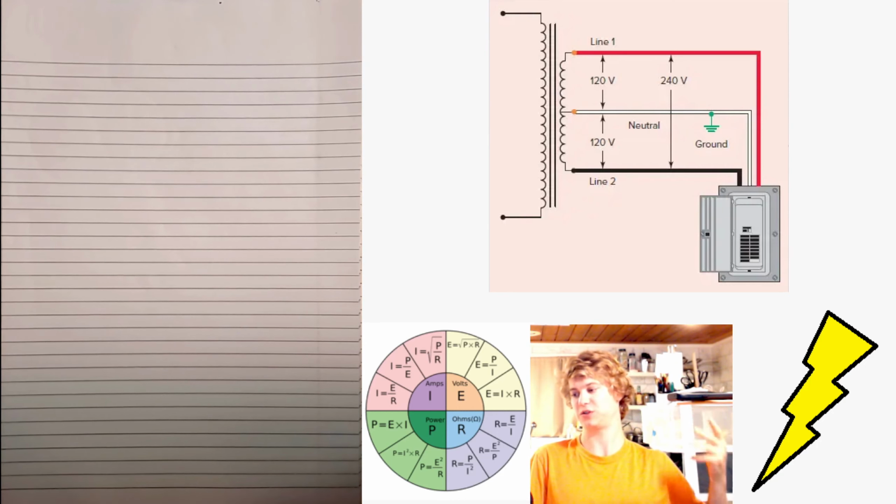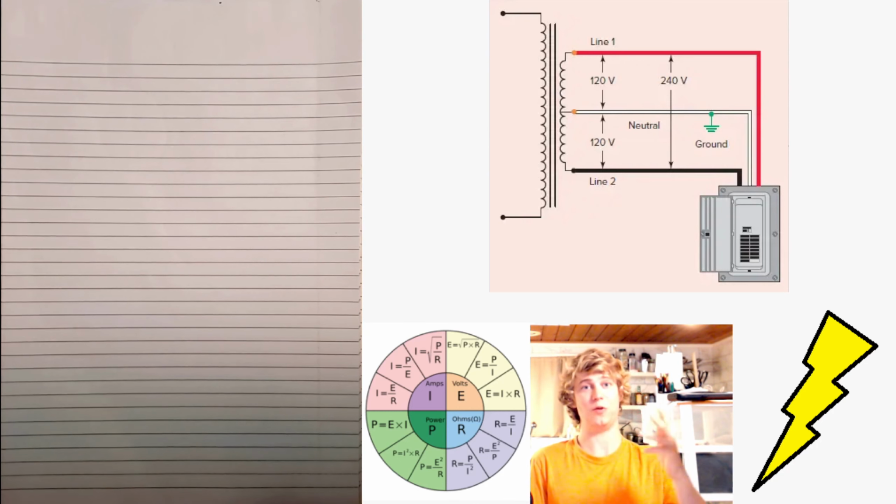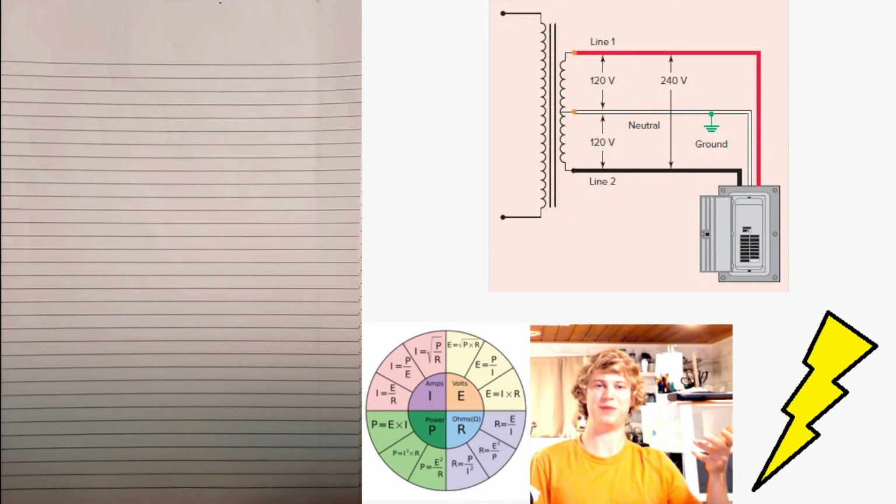On the other hand, most commercial and industrial electrical installations require three-phase distribution systems. A three-phase voltage supply is a combination of three single-phase voltages. Okay, so we can see the single-phase system. Let's think about line 1 with a neutral, and with a load we'd understand that the current would be flowing down line 1 and back on the neutral.